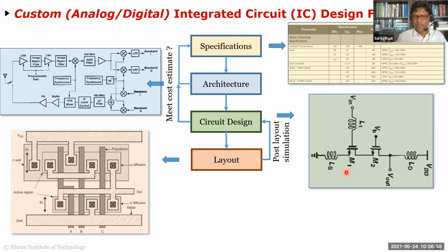Like from every node to another node, there is a parasitic capacitance, which is not captured here because you don't know how you're laying out, because there are a million ways I can lay out these two transistors, and I'll have a million different combinations of parasitic capacitance, and most of them will make my circuit completely dead, and some of them will not.